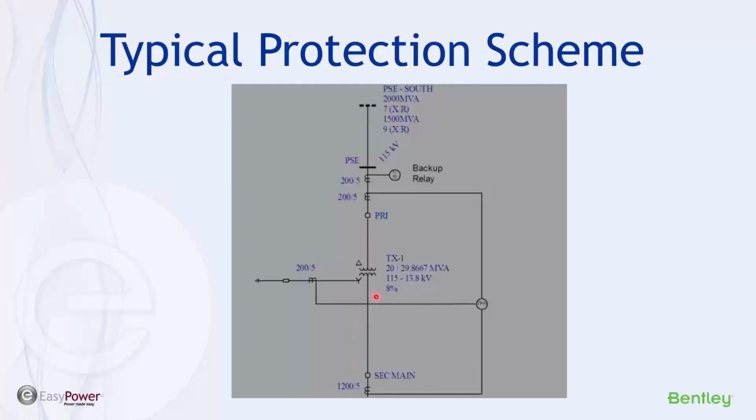And then as far as comparing this against a fuse, it can be considerably more investment, but better coverage. More investment because the relay itself can be expensive, the CTs have to be selected, and then the medium voltage breaker has an investment.